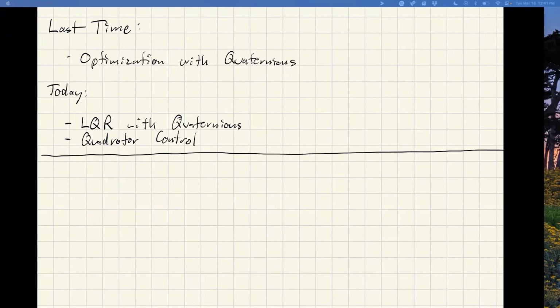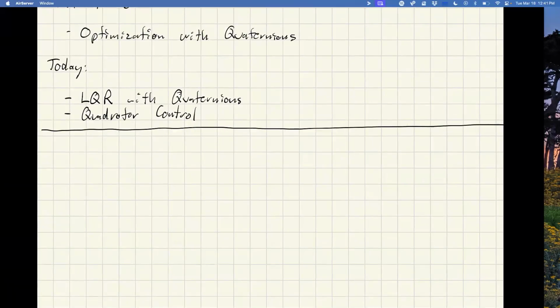It turns out these attitude problems admit tight convex relaxations in a lot of cases. One of those cases, by the way, is Wahba's problem. We can talk about this offline, but that problem is non-convex. But if you play some games, you can relax it into a convex problem that is tight, meaning the relaxation is always exact. And you can show that pretty easily. So it's an offline conversation; it's subtle, but you can do some stuff there. Sorry, I'm easily distracted. Okay, here we go. So LQR with quaternions.